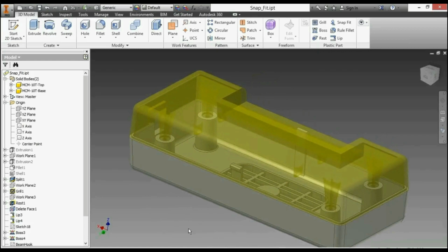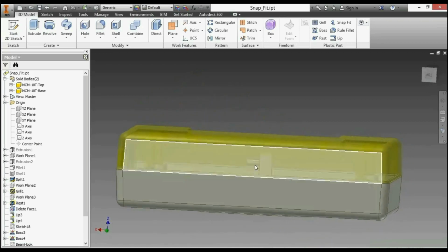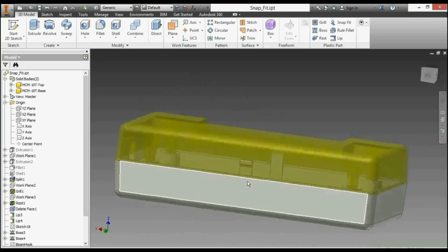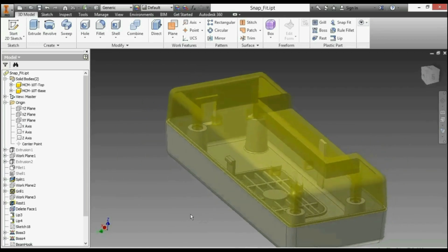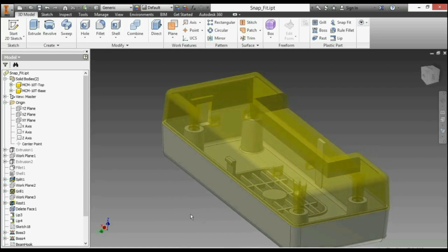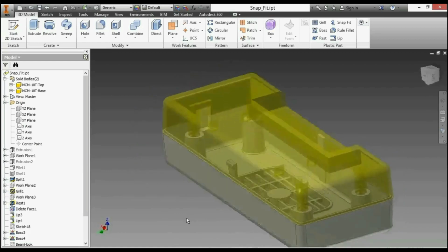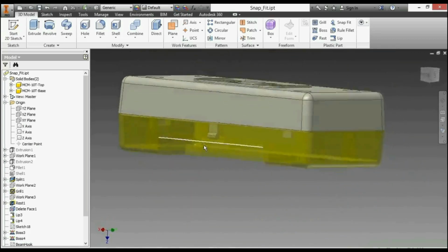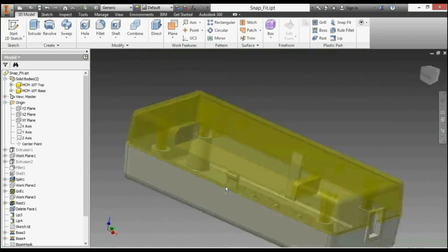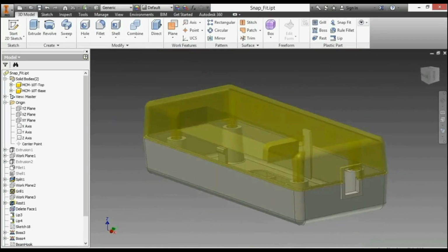So what I'm going to have to do is create an opening here, allow the snap fit to actually take place and catch on to my yellow geometry. So I basically need to do a little bit of extra work, making it so they actually snap together. But here you can see 2 different distinct reasons to use snap fit. So you can easily create some geometry on the inside for hooking other parts into, or to use for connecting your 2 parts to make sure they stay together.